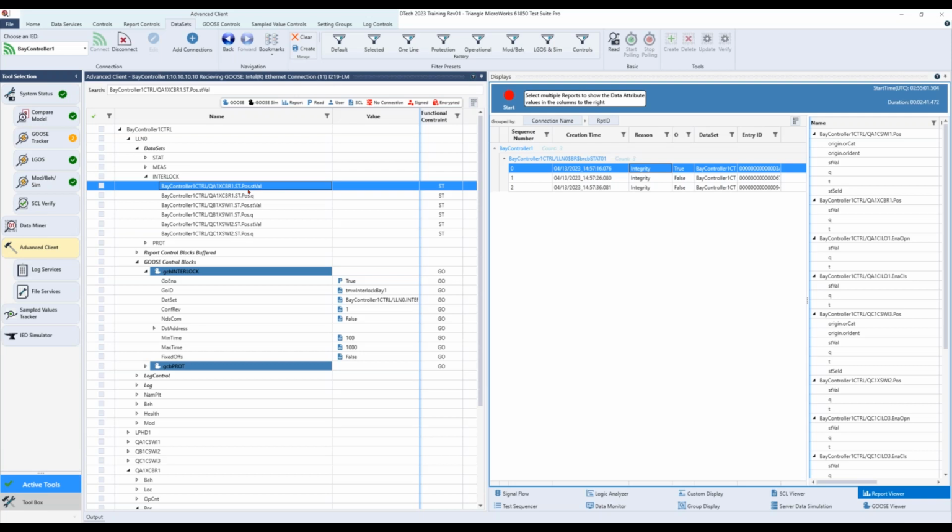To reiterate what Christoph said earlier, and one of the questions that we received during the break, GOOSE is the high-speed messaging system that's meant to replace wires, and it typically goes from server to server, whereas MMS or report control blocks is still speedy, but not as fast, not in the millisecond range, and is typically used for vertical communications, which go from a server or IED, say a protective relay, up to a SCADA system.